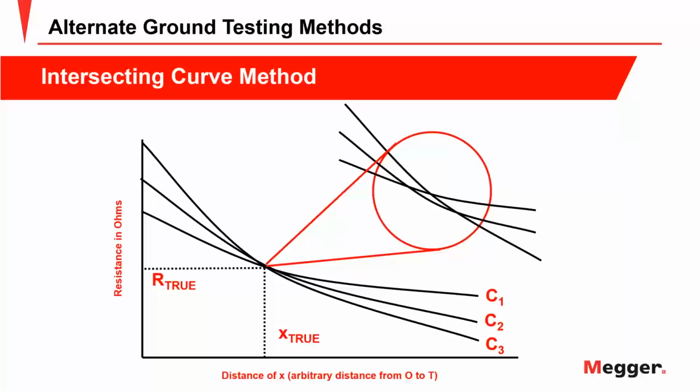And so the point here is that somewhere on those 3 lines, there is actually the correct resistance reading at the 62% point. You don't know yet where that is, but it's got to be there somewhere because you picked various guesses across the reasonable range of distances. And so the 62% is in there somewhere.